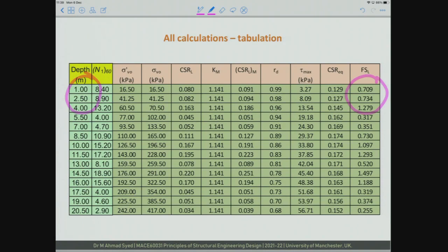Likewise, if your structural calculations say that yes, shallow foundation is not good enough, but you still want to provide a foundation, you are going deeper into the ground, then perhaps say from your calculations your pile is going to be 7 to 8.5 meters. Then again at this depth liquefaction is likely to happen. So perhaps you may need to avoid this depth and go further deeper into the ground. So this also dictates the depth of pile foundation that you may have. Then one interesting thing that we get from here, so that is the relevance of developing this profile with regards to the type of foundation that you are going to construct. Then one interesting thing over here is something like this. Sorry, not this one.